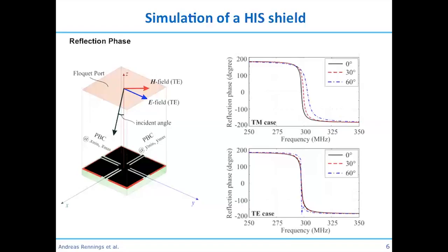And for very high frequencies, the capacitors here are short-circuited in an RF manner. And again, we have a PEC behavior. But in between, at this frequency here, we have a 0 reflection phase, and that's really what we want to have. Here we checked out the dependence of the reflection phase on this incident angle here.